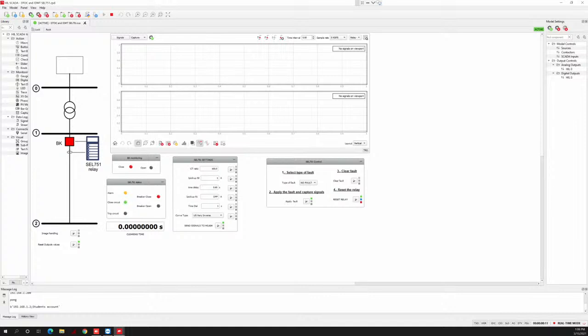Just here, these signals, alarm, closed circuit, and trip circuit, are measured directly from the SEL-751. What she is telling you is that these are real signals, measured at the back of the relay. When the relay is on, you can see here some LEDs, okay? But those LEDs are for local information. You can send that information somewhere else if you are able to identify the cables and the connections and so on. And we are taking that information and sending it back to the real-time simulator, okay?